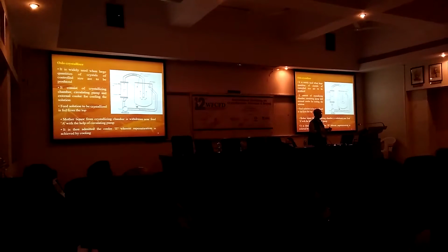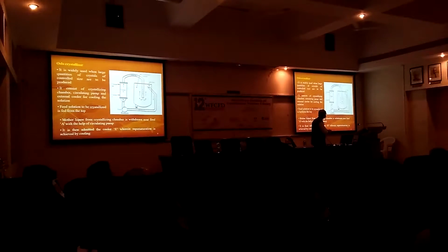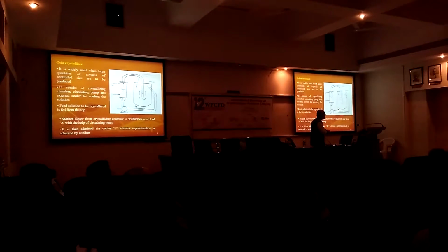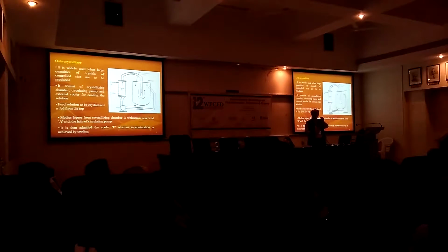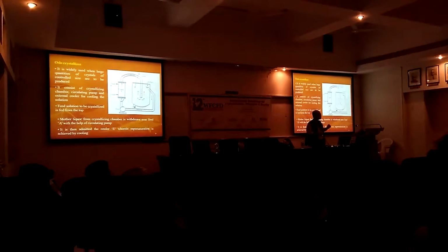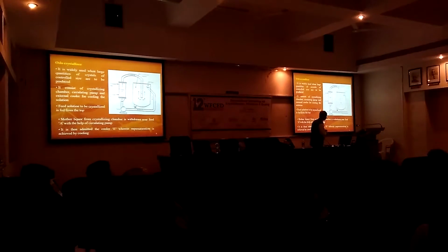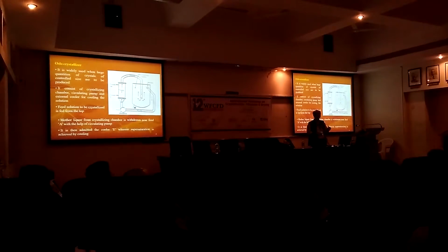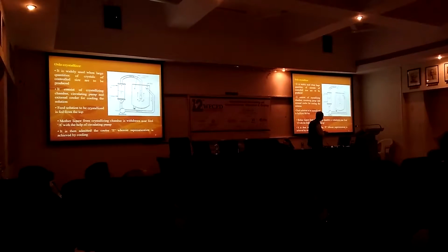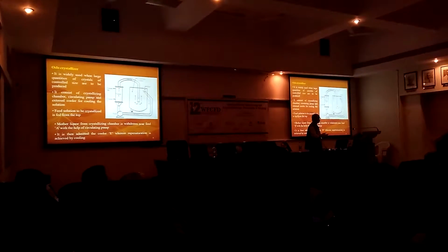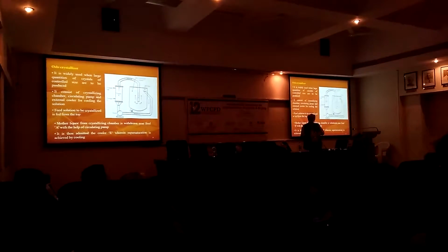Now this liquid flow pattern will essentially segregate the crystals. Smaller size crystals will occupy the upper location, and larger size crystals, because of their higher settling velocity, will take up the lower position. So if you keep on taking out material from the bottom, essentially you will be collecting larger size crystals. The smaller size crystals are likely to get recirculated. They will be exposed to supersaturation again.